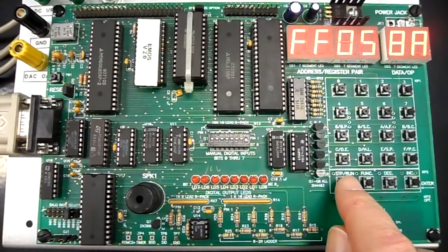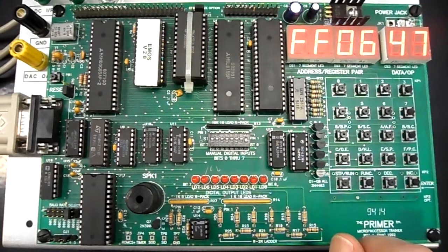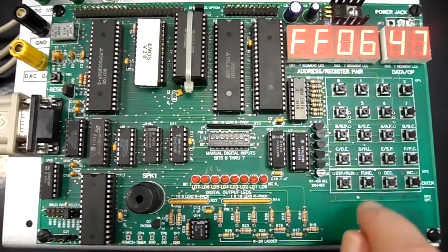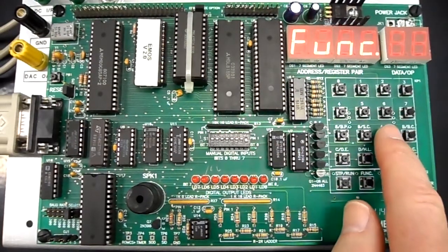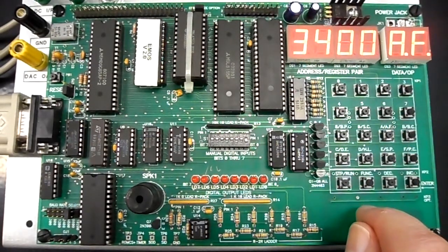So at FF05, I'm going to press step, and the D register and the carry flag are to be added to the A register. So in this case, we're looking for the number 34 in the accumulator. So if I press function AF, we can see that 34 is loaded into the accumulator. All the flag bits are 0, and we said the auxiliary carry bit was now going to be 0, the carry bit is going to be 0, and the parity bit are 0. So it's done all that according to our calculations.